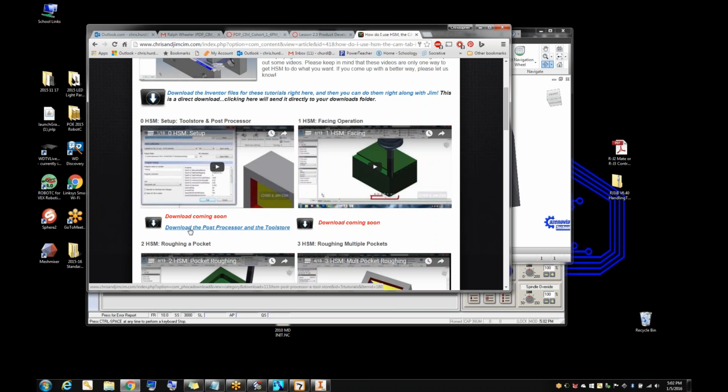And some years, if you have some extra time, I'll have kids who say, hey, I want to stay at lunch and I want to do this, and it requires two tools. I'm more than happy to let kids do tool changes, but when I'm trying to do mass production, like Jim said, you limit it to one or two tools, and it just cuts way down on the time. It also cuts down on human error with the kids putting their hands into a CNC machine to swap tools in the middle of an operation. As you saw from that video, I have a lot of gray hair. Each one of those came from a kid doing something on a CNC machine that he shouldn't have.